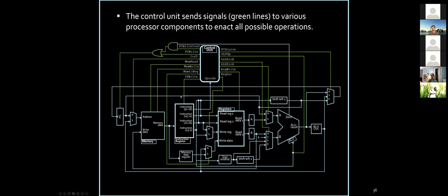You already learned about these control signals when we learned about transistors and how we build, say, the register file. For example, this is a flag for register write, whether we write or not. Remember, how we manipulate the register file depends on whether it's read or write. Since that's important, there is a flag that we can put in to enable different data flow into the register file, and I showed you that before.